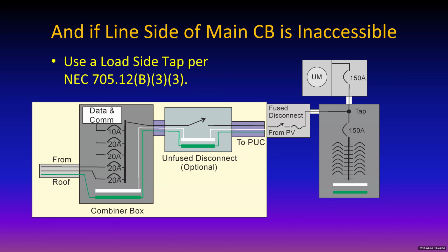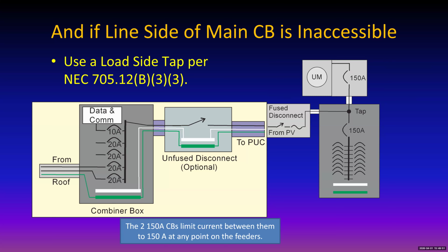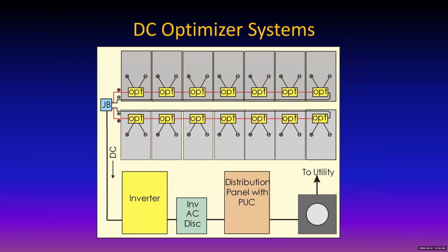And the first power that goes to that bus bar is from the solar. And anything the solar doesn't need then is made up by the utility. Okay, so there's that connection. In that 150 amp circuit breaker at the top of the other says that the sum of the current from the solar plus the utility is still not going to exceed the rating of that panel.